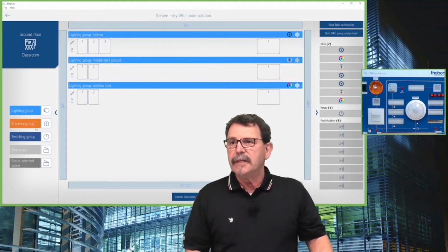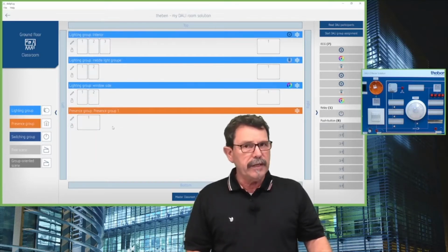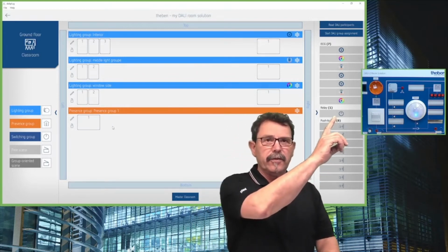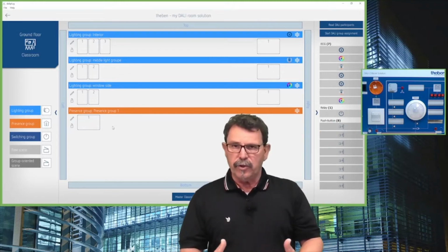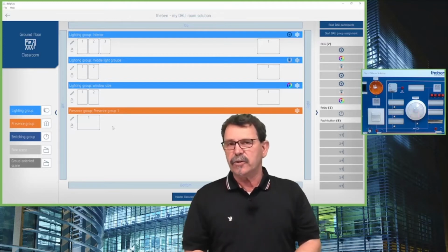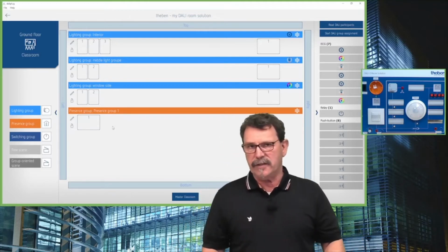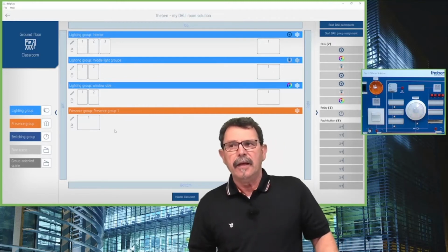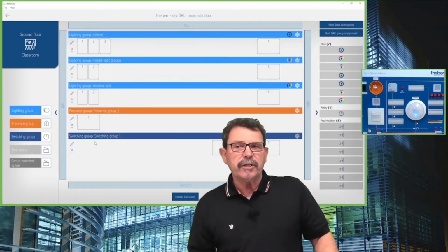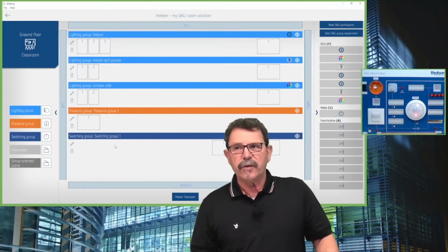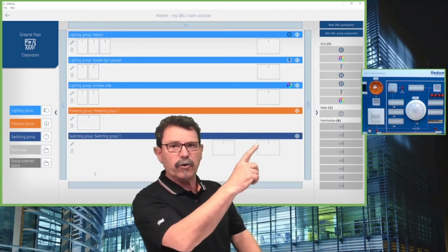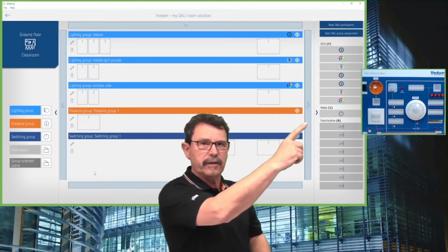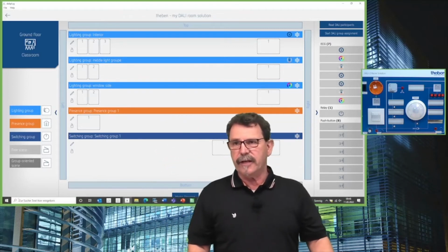So far so good. Now we do have here a presence group. Presence group means we can now implement this one here, relay. So that means whenever someone enters a room, a person as an example, then, for instance, ventilation or such is starting according to your presence, if you like. If you want to switch a fan manually, then we can use, as an example, a so-called switching group. A switching group consists of a switch and a relay, which we have to allocate finally.